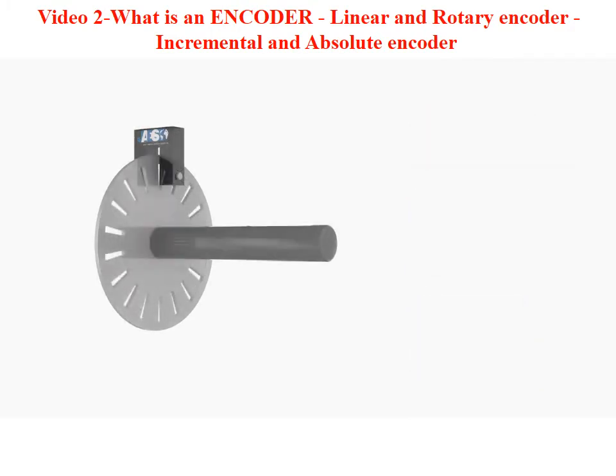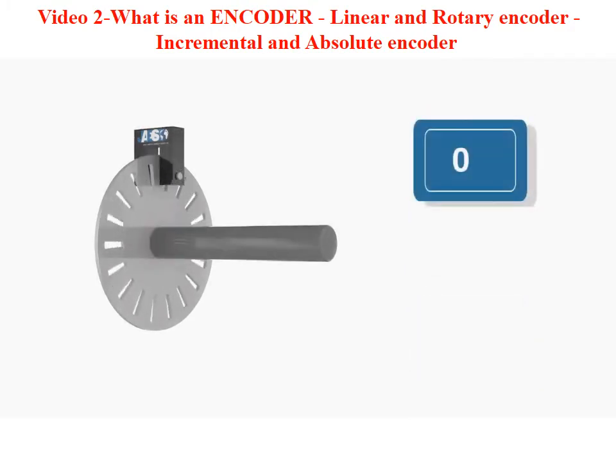Incremental rotary encoders create an output signal every time that the shaft rotates a certain amount. This output signal is then interpreted based on the number of signals per revolution. This encoder begins its count at 0 when powered on, so there are no safeguards regarding the position. That's because, unlike the absolute encoder, the incremental encoder begins its count at 0 at startup or power disruption. For this reason, it is necessary to determine a reference point for all tasks requiring positioning.